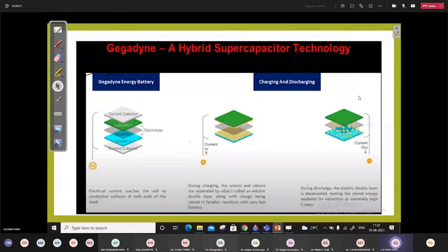Here the advantage is that only one bidirectional converter is required, but the disadvantage is that because we are using it for supercapacitor, as the supercapacitor terminal voltage reduces, to maintain that current, the current rating of this bidirectional DC to DC converter will increase, because we know that when voltage decreases, current has to increase to maintain the same V into I product. So this bidirectional DC to DC converter must be of a high current rating when the supercapacitor voltage reduces from its rated voltage. That is the disadvantage, but it provides a very good control for this supercapacitor.